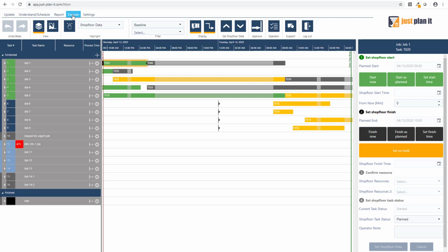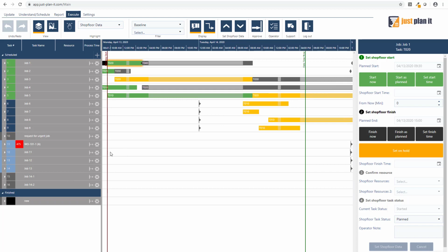This automatic scrolling has two lines or dates that are taken for this automatic scrolling. So at the left hand side you can see that the right planning start line is taken as the left border here, and on the right side the time now line is taken for the automatic scrolling. And that is on purpose, because within this time window between the red and the green line, the potential progress can be done.